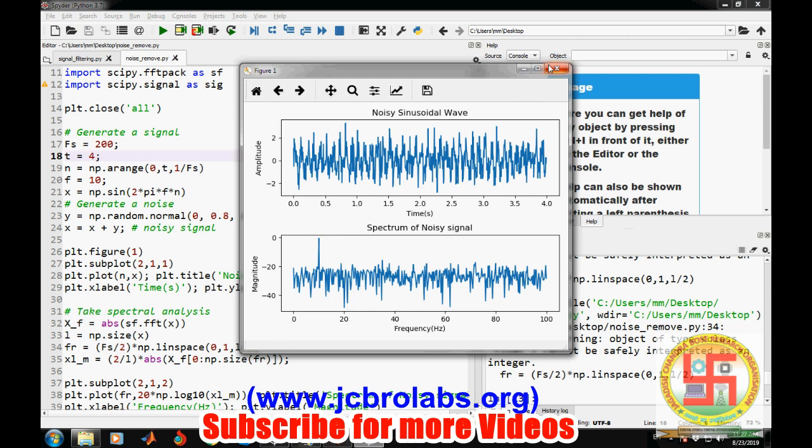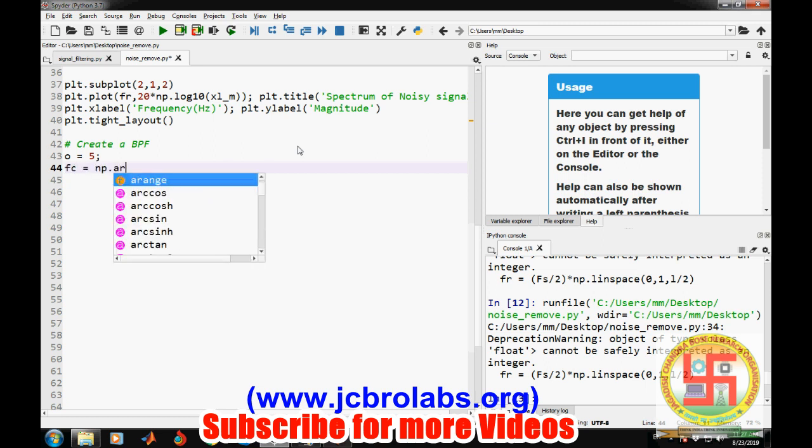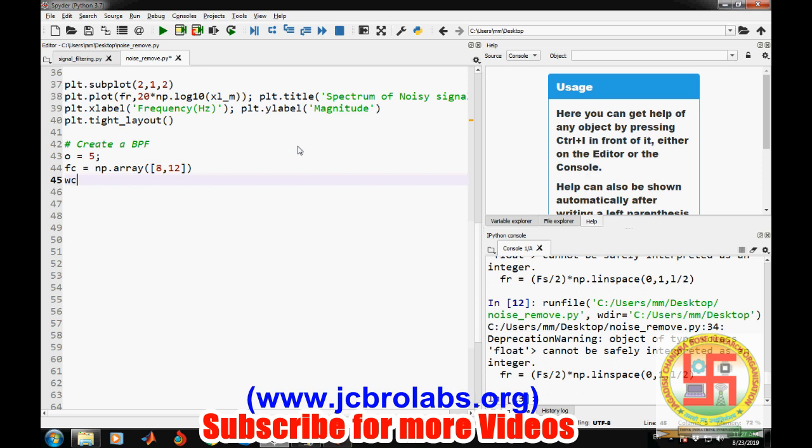Now we'll create a filter. For that we need a band pass filter. In our previous video I talked a lot about how to create filters in Python, so if you want, you can go through that video as well. First, to define the filter, we need the order of the filter and then the cutoff frequency of the filter. The cutoff frequency is an np.array, because the signal is 10 hertz, so we want it to be from 8 hertz to 12 hertz, so that it comprises the 10 hertz signal within it. Then we need to normalize the cutoff frequency, fc divided by fs.